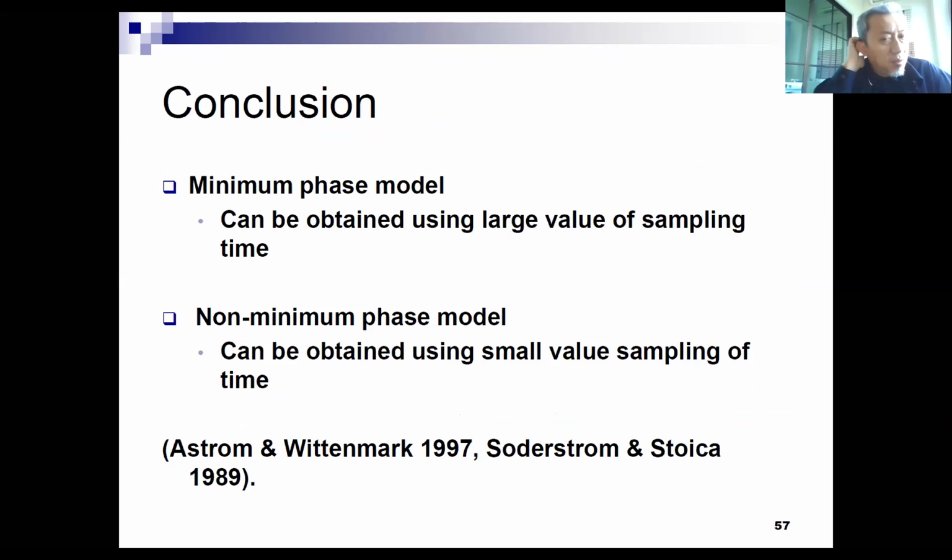So the conclusion is: a minimum phase model can be obtained using a large value of sampling time. A non-minimum phase model can be obtained using a small value of sampling time.